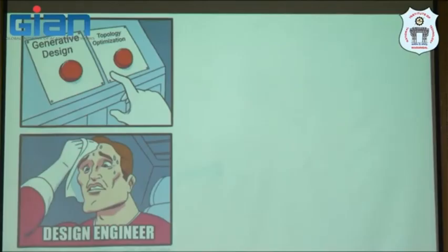There is only one software working on generative design, that is Fusion 360. But for topology optimization, many software packages are working. In generative design, we enter a prompt. I am using ChatGPT terminology because right now we don't have the software. But we will see topology optimization. We enter the prompt, meaning we give some constraints and objectives, so that according to that it will generate the 3D model. That we call the AI models, artificial intelligence models.